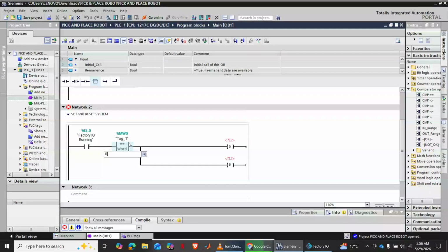right? So here we said when it's 00, like when you don't have any memory of the counter on the system, start the conveyors. Alright, all conveyors should be on. When we start the counter, when we increment counts, then we will rewrite another sequence of what should happen, because this plate or raw material conveyor will continue bringing raw material onto the stackable box, and once they reach 3 it will allow the stackable box to move away, we bring another stackable box and then we keep picking and placing.